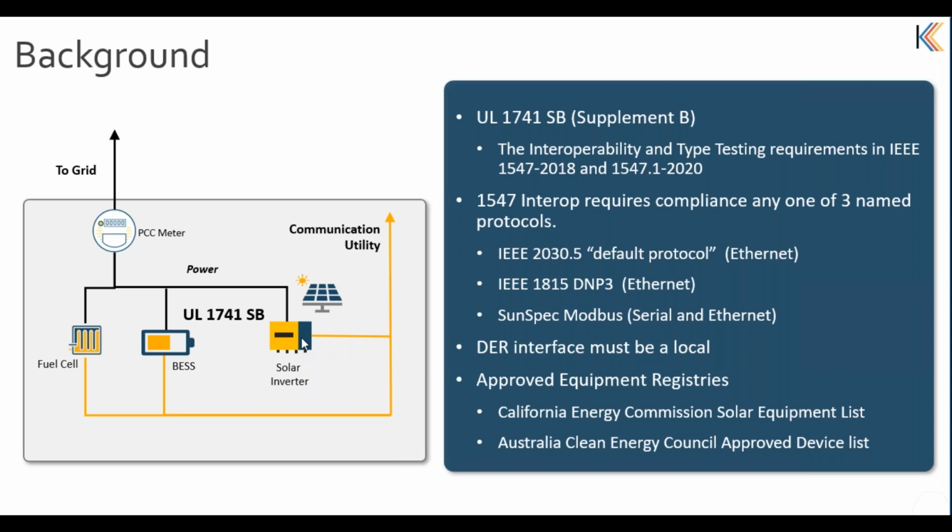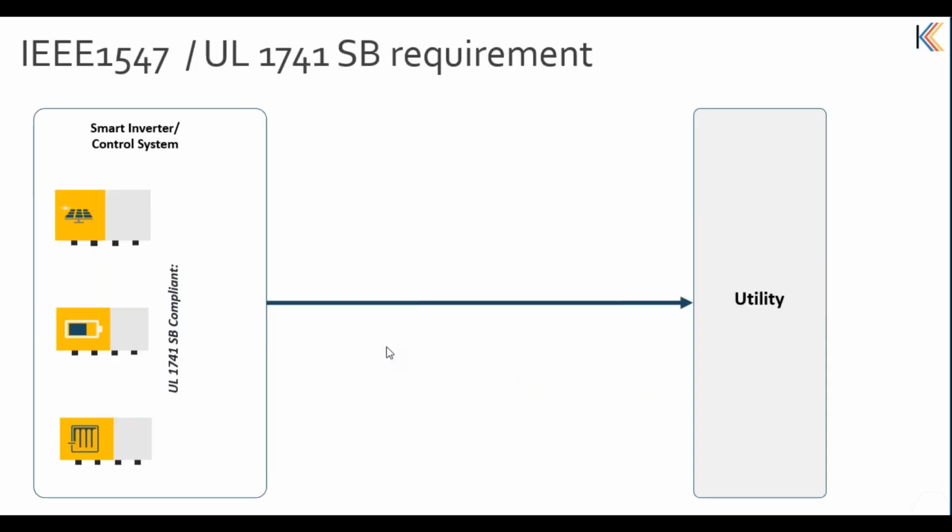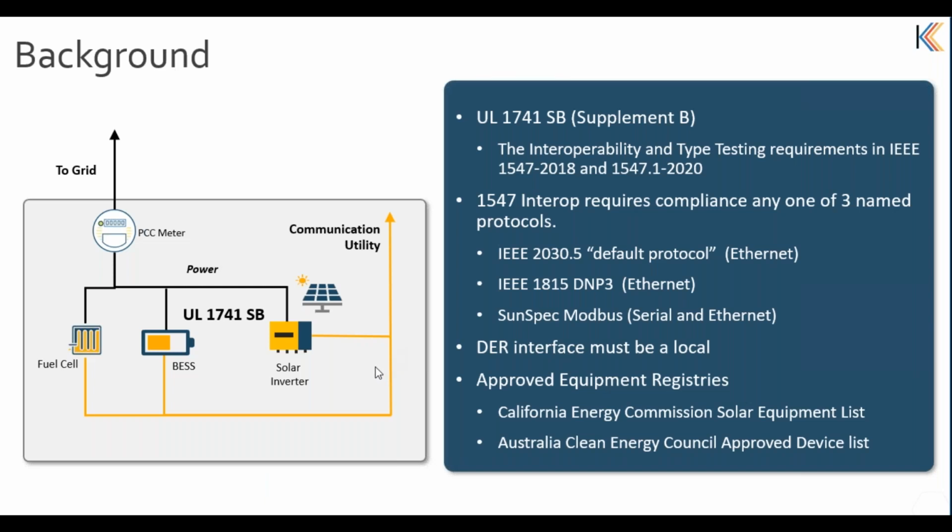So interoperability testing as per 1547 just validates that the messages are received properly and properly understood by the DER. It is not purely protocol conformance testing, but actually functional testing, which can be done through a communication interface.